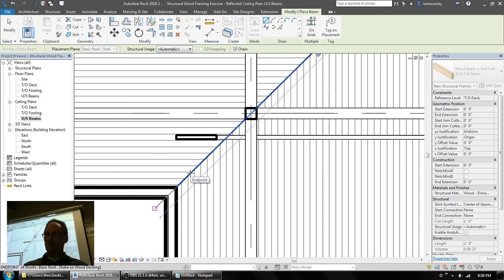And it's our view range right now. It's the cut setting of our view range, which is causing our roof to be truncated. So that's where we want to go, just like that. Not like this, not like, I don't know, whatever else. Just want it to be there. And now you can left click.